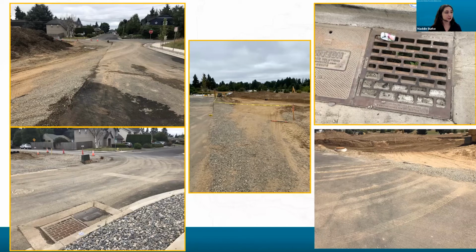And then in this picture on the top, there was a witch's hat installed into this catch basin, but it's not being maintained. And you can see that concrete has gotten into the catch basin, and there's even a plant growing in the sediment buildup inside that witch's hat. So just including inlet protection to install once is not sufficient. This last photo here is a second part of the site where vehicles were using a non-approved access to enter and exit the site. So here are just some of the things to consider of what can be a problem with sediment leaving the site and with water resources being protected.